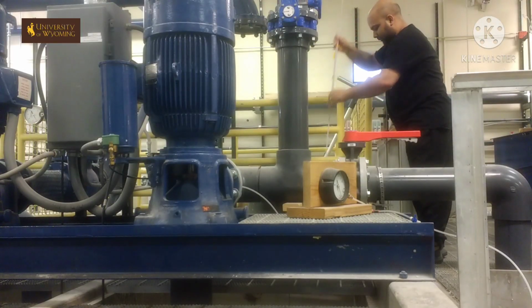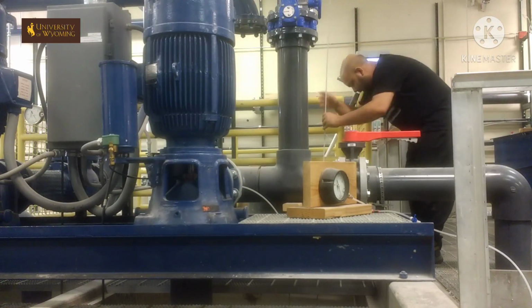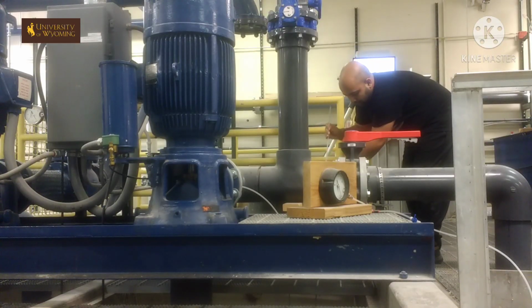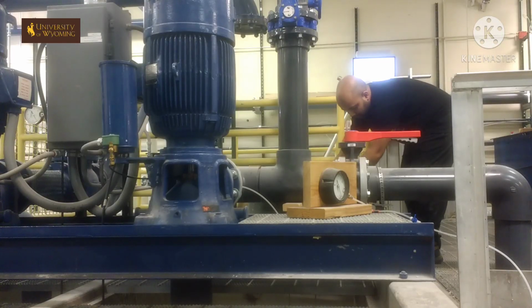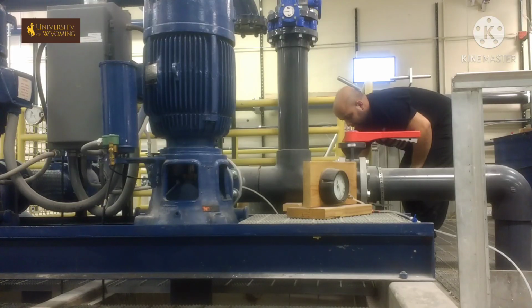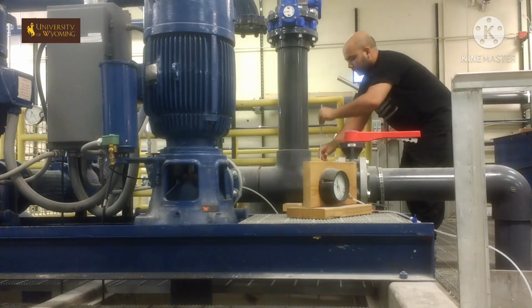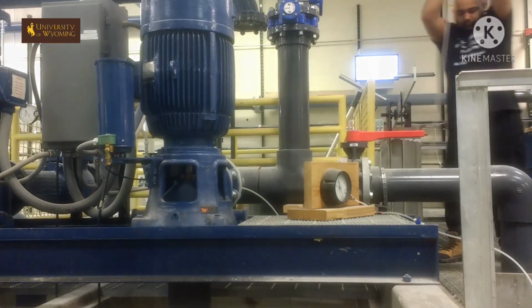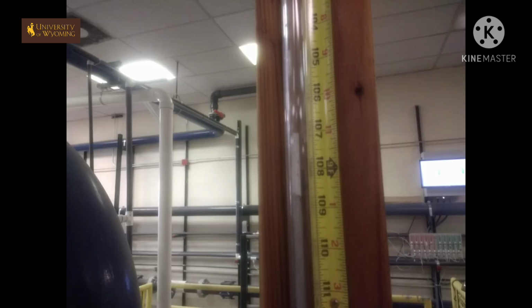This is the pump, and the reservoir of water is underneath the pump. First, we need to measure the depth of the level of water from the center line of the pipe. For this, we use a long rod and dip it into the reservoir. Remember, our reference point is the center line of the discharge pipe. Then we'll measure the depth using measuring tape and the rod.